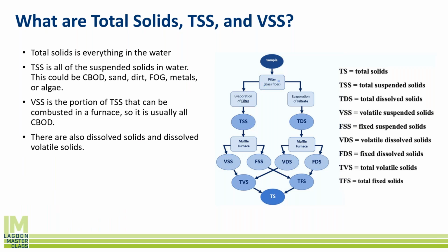Now, we can do the exact same thing for dissolved solids. Basically, they'll do the exact same test, but instead of taking the filter, they'll take all the liquid that passed through the filter, and they'll do all the same things again. This is really important because by looking at dissolved solids versus suspended solids, we can determine: is there a lot of dissolved salts, for example, or is it suspended solids like algae or dirt or things along those lines? So it becomes very important down the road for diagnosing potential problems.